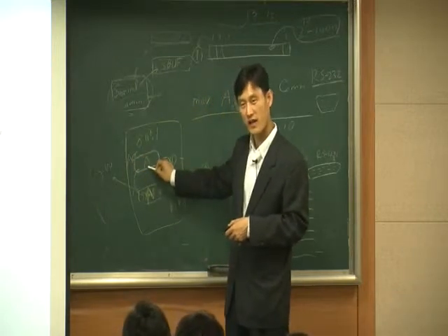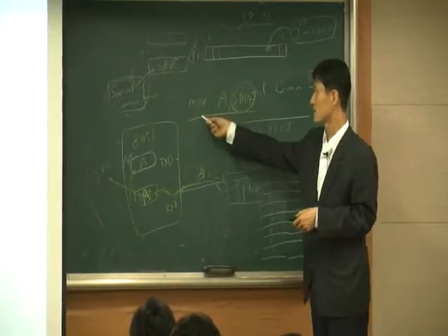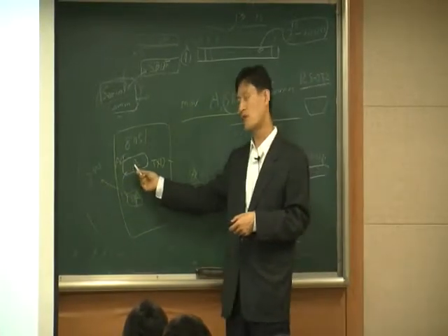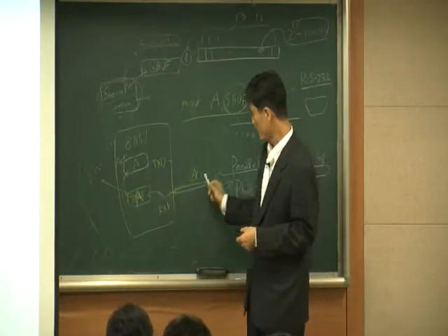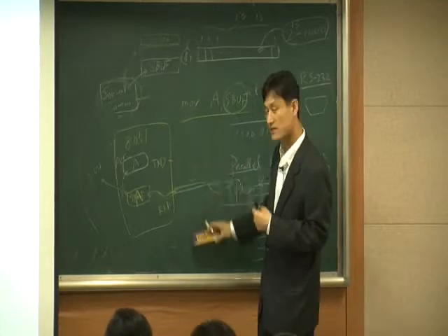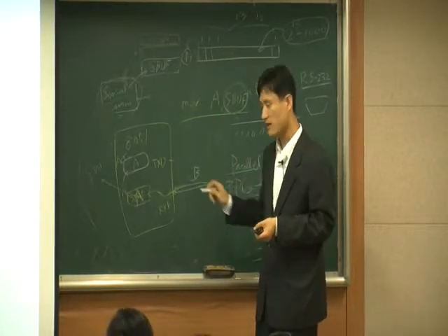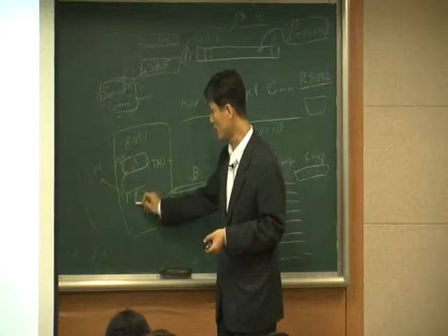Now I have the value A in the accumulator, because A was in SBUF. When you do this, the value is copied. Then a little bit later, let's say this guy transmits the next data, B. Then again, this one is updated with B.